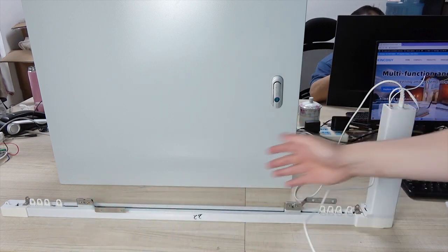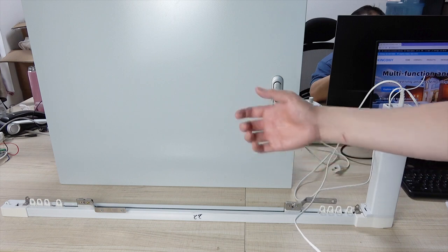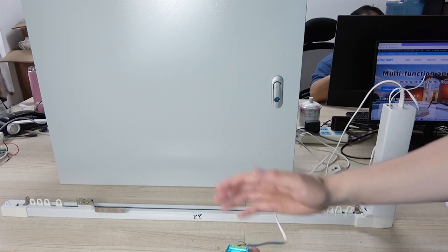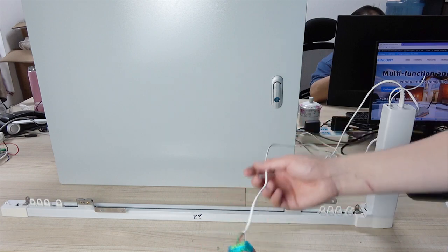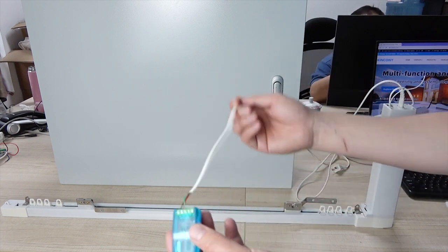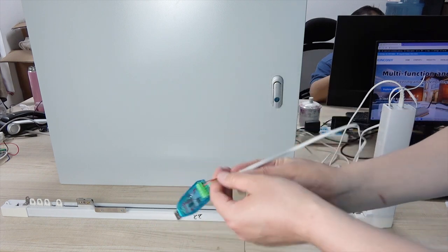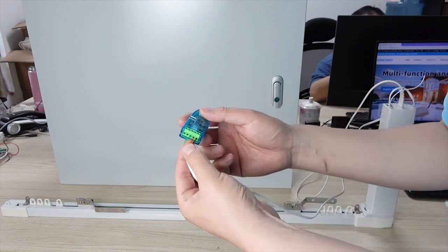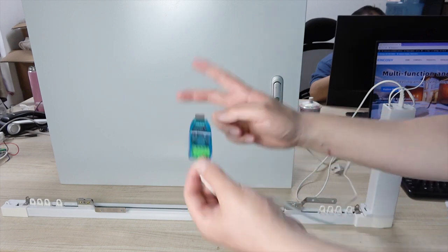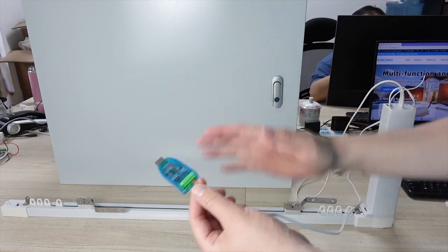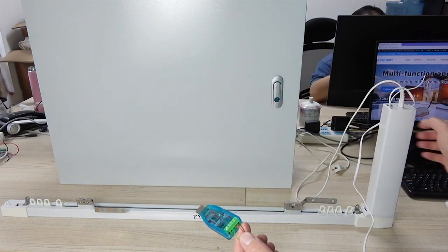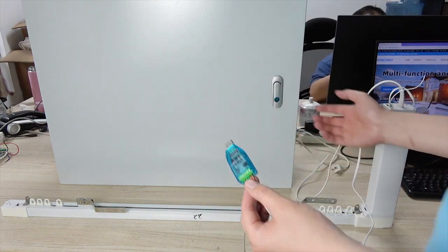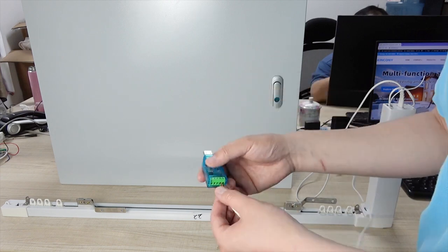Because if you have many motors, many curtains, and you install a wall switch and connect with a relay controller, you will need many of them. But if you use a motor that has the RS485 interface, this cable, you just use these three, or these two, for A and B and ground. Actually, you can use just A and B, two wires, so you can connect them together. So many motors can connect together. So just send the command by yourself. Your application can send the RS485 protocol command.